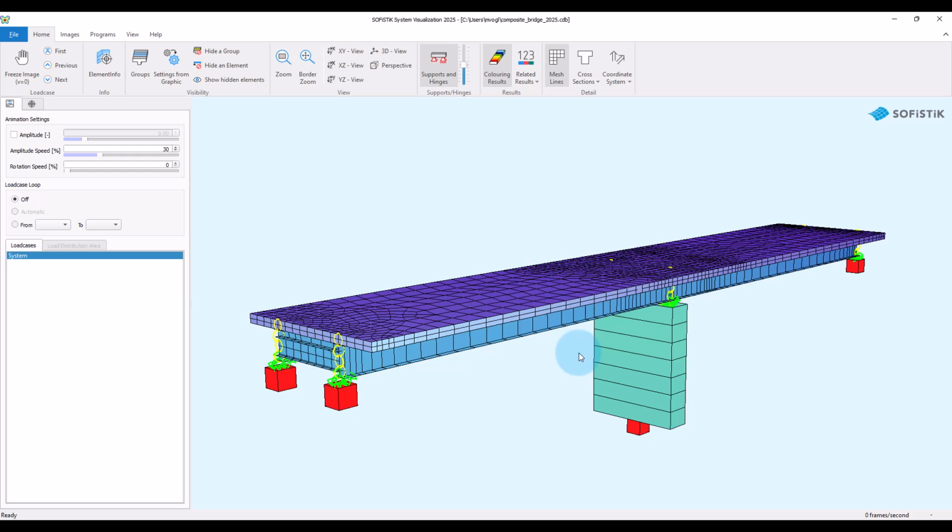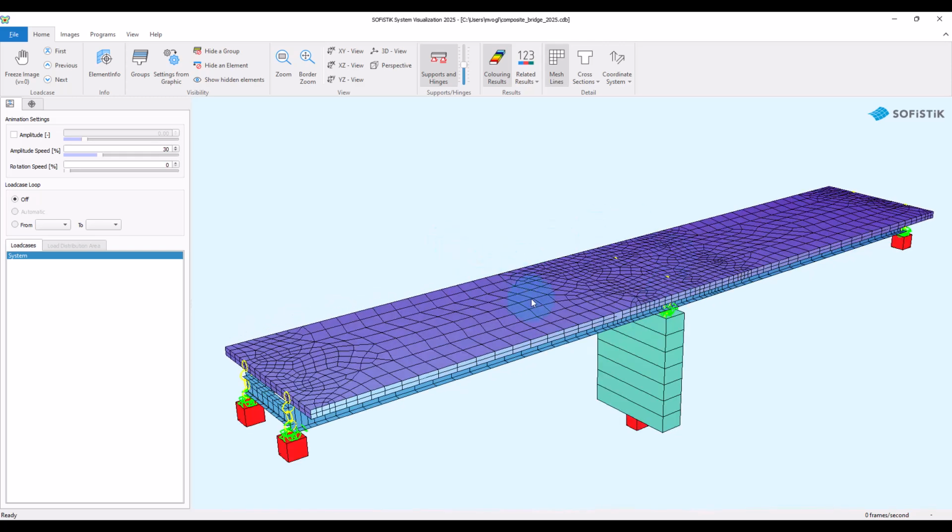As you might remember, we handled this topic for the self-weight by assigning the area elements a concrete material with zero weight. The topic of the stiffness we will treat now. The idea is, because we focus here on the design of the main girders, we need the area elements only to connect the girders and to apply and distribute loads in cross direction. Therefore, we will switch the stiffness of the area elements in longitudinal direction off.